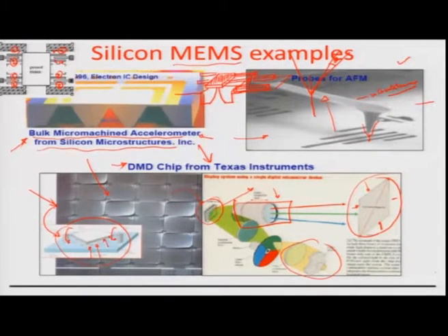whenever there is a motion in terms of rolling, pitching, yawing, etc., of these proof masses, there is going to be interfacial capacitance change, which can be calibrated with respect to the acceleration or deceleration, and that results in an actuating signal which can open up a nitrogen bottle which can otherwise fill up the airbag.